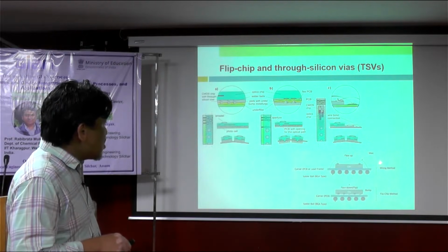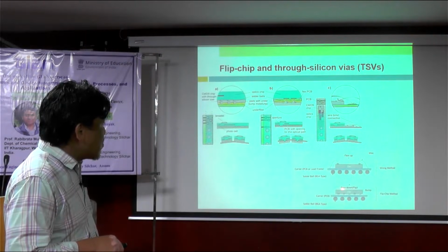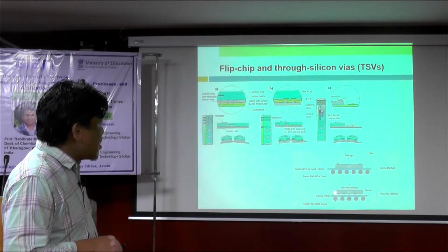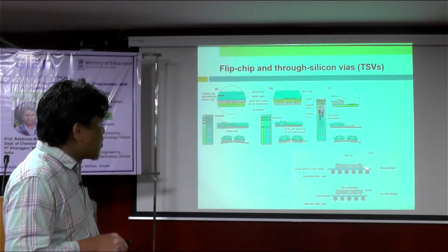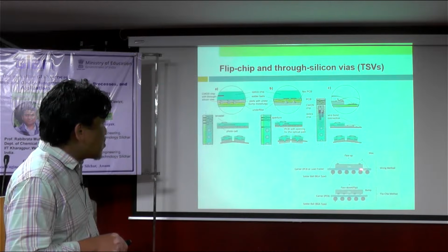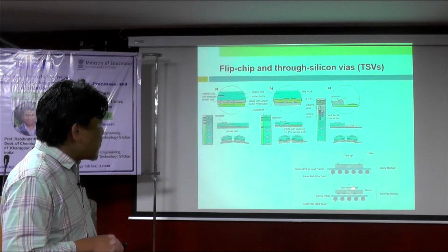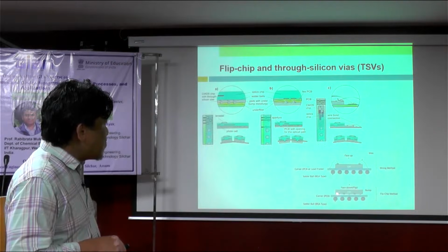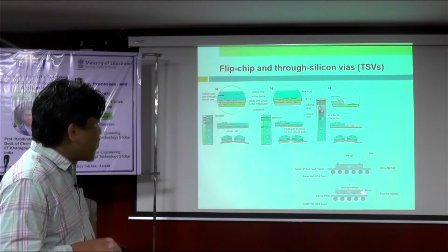So here is the difference between wire bonding, as I mentioned before, and the flip chip design. Here you have to bond using wire bonding to the outside, to this pad, using wire. Instead of that, you have a flip chip connected directly using solder bump, for example.